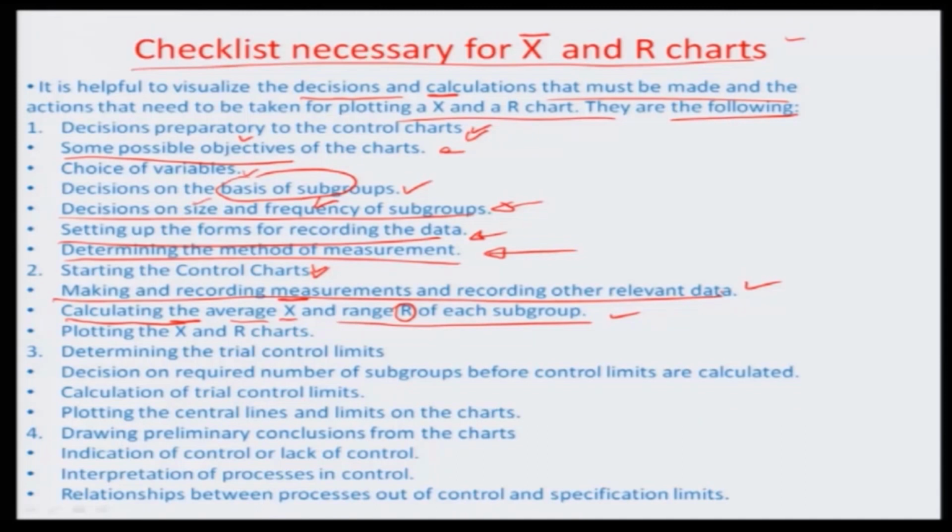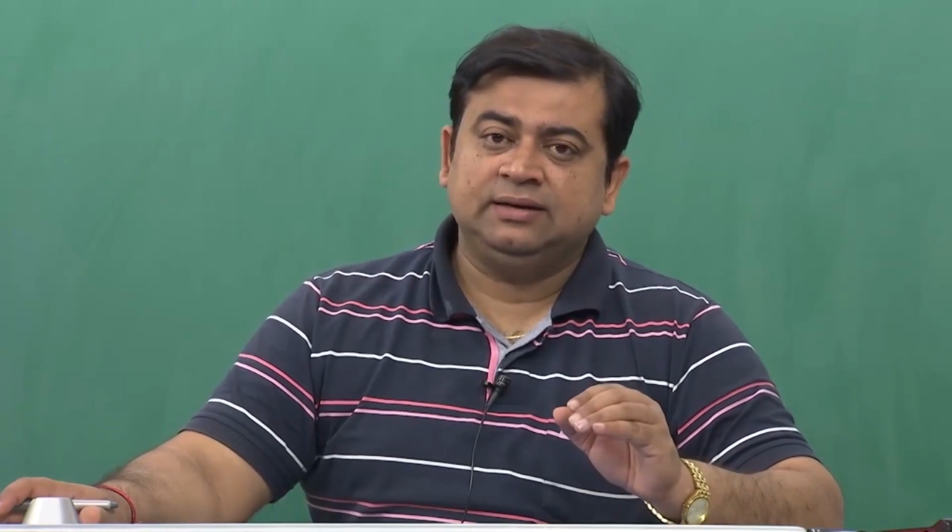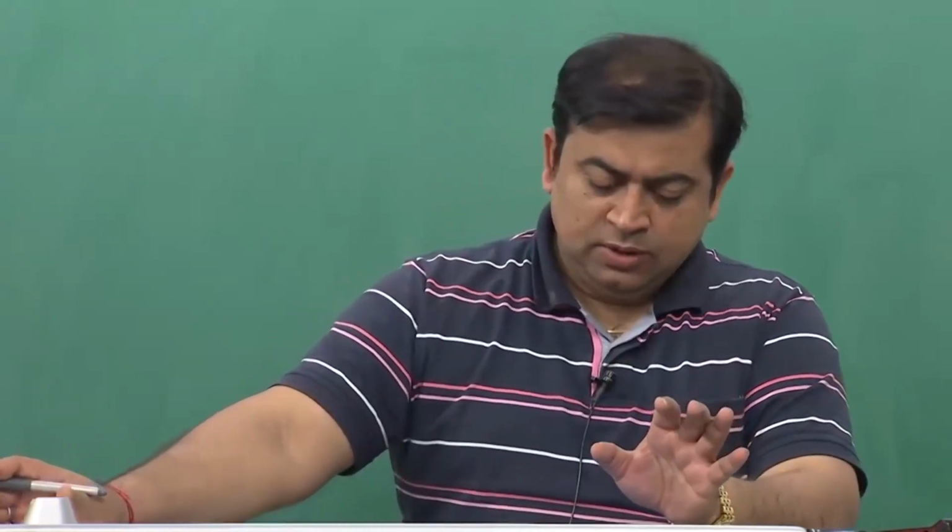So, as a supervisor you have to provide these measurements and subgroups in a very honest and integrated manner, and you should be able to justify why you are choosing a certain group size and a certain frequency of grouping, in terms of the possibility of occurrence of some defects, which you may see over a large time horizon from time to time.